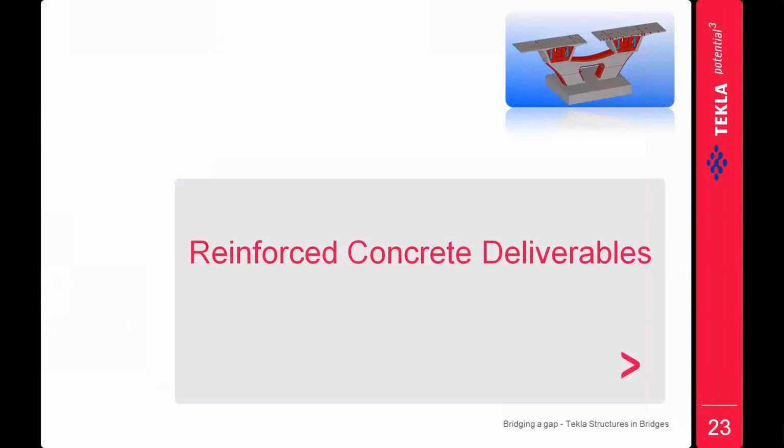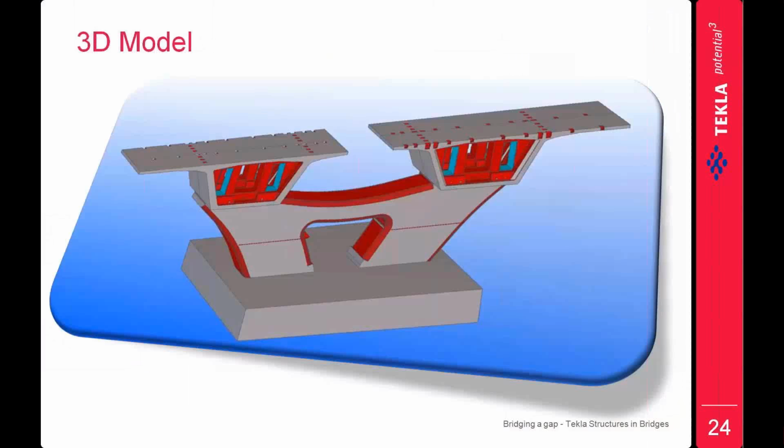And then on the deliverable side, what we are going to deliver from the Tekla Structures model, the first is the 3D model. Because it is an intelligent model, it has all the information in it, like the grade of the concrete, size of the rebar, the shape code, and the chainage details. So we can send the whole 3D model to a third party, like the site people, so that they can open the model in Tekla BIMsight, which is a free tool from Tekla. They can open the model, check, comment, and reply back to us also.